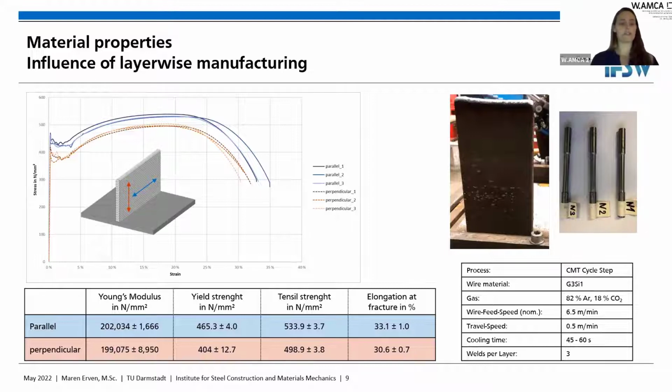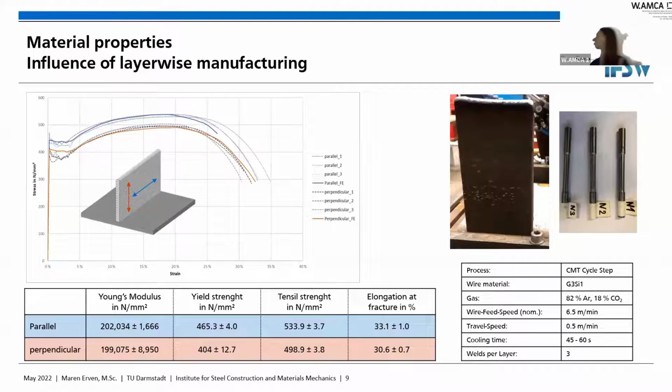And the yield strength is then different to each other, and also the tensile strength, and also the elongation factor. I tried to use it for a material model, and there I use the Hill's criterion, and we can see that we can calculate it quite well, at least until the tensile strength.